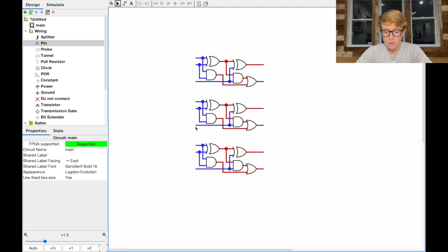Now the other thing we're going to do, the reason that this carry in was so important, and why it was a problem that we didn't have it with our half adder, is that we need our carry out from the lower bit value to propagate over to the carry in on our next place up. So the carry out from the 2 to the 0 place is going to need to propagate over to my carry in for my 2 to the first place.